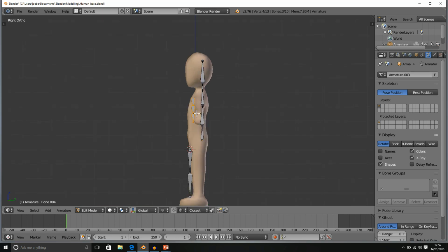Make sure that you're in a two-dimensional perspective. I'm going to press G. I believe we're along the y-axis, and I'm just going to move it, there we go, just in line with our arm itself. And now I'm going to do the same with our leg bones. So I'm going to just grab Y and just bring it back. Now I'm going to select this bottom joint, and I'm going to do one more extrusion for the foot.